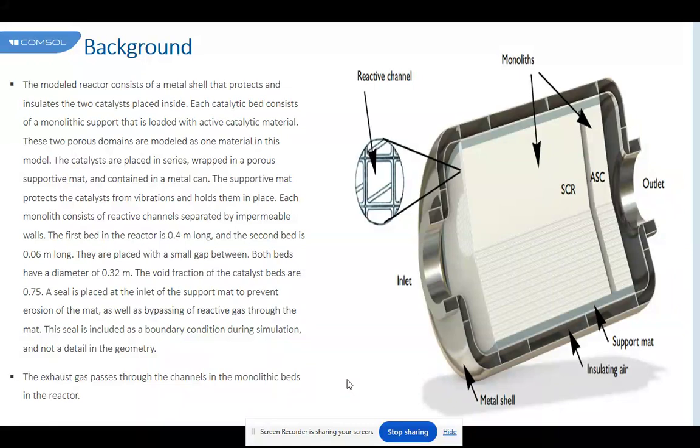The flow patterns in the dual cell density monoliths were successfully analyzed. The main conclusion from the simulation is that a monolith with a mixture of the two cell densities can in fact lead to a better or worse result than that from using either of the two cell densities individually. It is reasonable to expect that a result from using a combination of two cell densities would be obtained from the interpolation of the results from both cell densities individually.